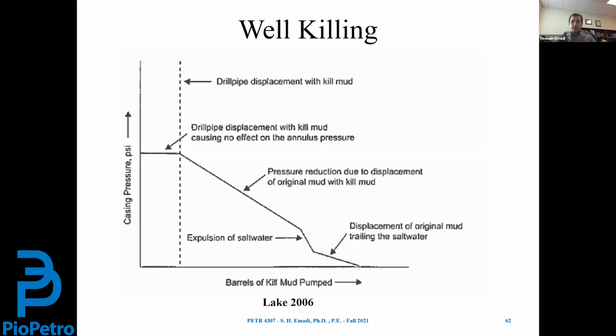The previous slides were about when the formation fluid is gas. However, when the formation fluid, for example, is salt water or oil, the behavior of the casing pressure is different because unlike gas, which is highly compressible, salt water and oil, we treat them as incompressible. What happens when a kick happens and the formation fluid is salt water, and we are obviously implementing the wait and weight method, as you can see here, since again